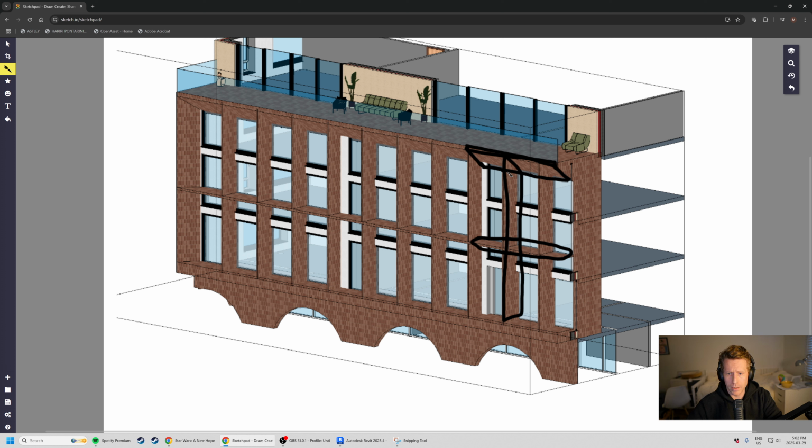So imagine now these spandrels, we actually have to split them, right? Mullions don't necessarily have to be just mullions. They can just be joints or gaps within our panel system. So imagine that this is a little piece, this is a little piece, and we're going to start to split up our assembly into these little panelized sections. So curtain wall is really just a set of panels. The complicated part is figuring out how many panels we need to represent all of these different conditions.